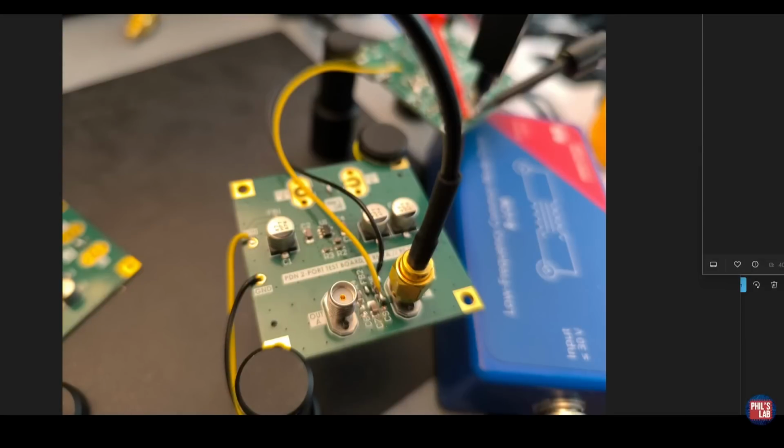It's a very simple, very crude test setup. All I'm doing is taking our usual PDN 2-port test board, taking one of the SMA channels, feeding that directly into channel 1 of my oscilloscope, and that's to monitor the output voltage noise. I'm powering this board using the input and ground leads from a Rigol power supply set at 5 volts, and the outputs I've just soldered on directly via some cables to a spare board I had, which had a FET and a couple of load resistors, which I'm using as my switchable current source or current sink, and that's been driven by a Siglent wave generator that's connected to my oscilloscope.